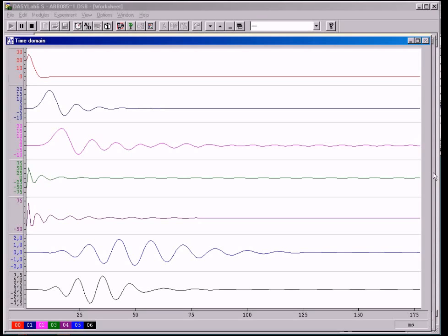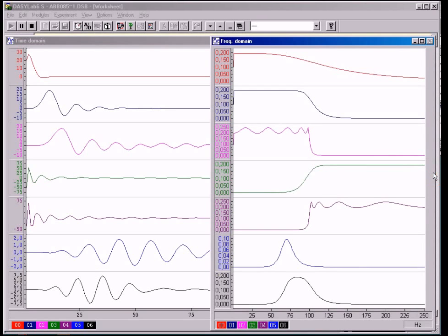In order to obtain the frequency response, the pulse response must simply undergo an FT. As in the case of the delta pulse, all frequencies have the same amplitude. The amplitude spectrum of the pulse response forms the curve of the absolute value of the transfer function.